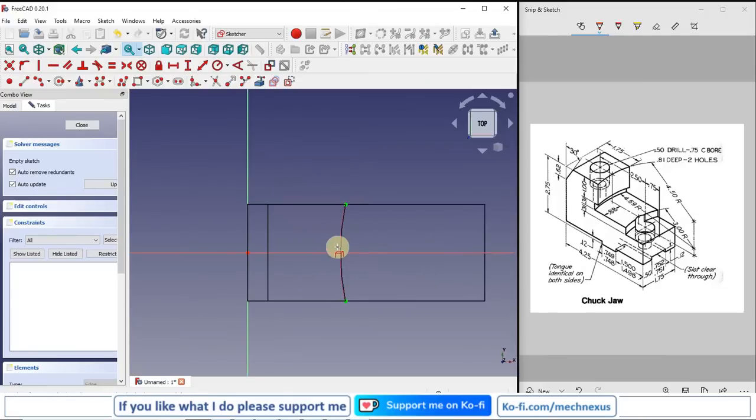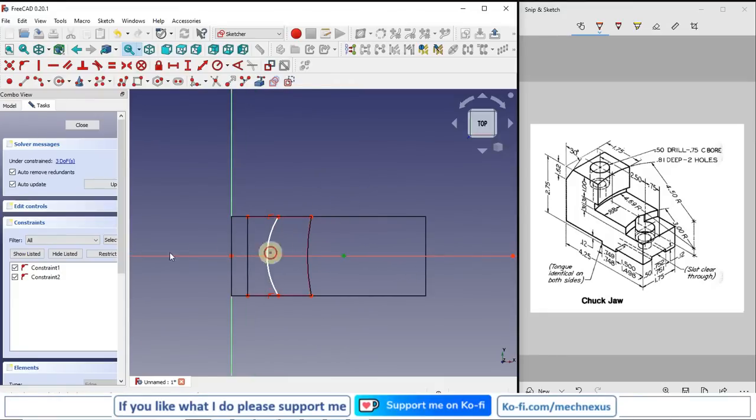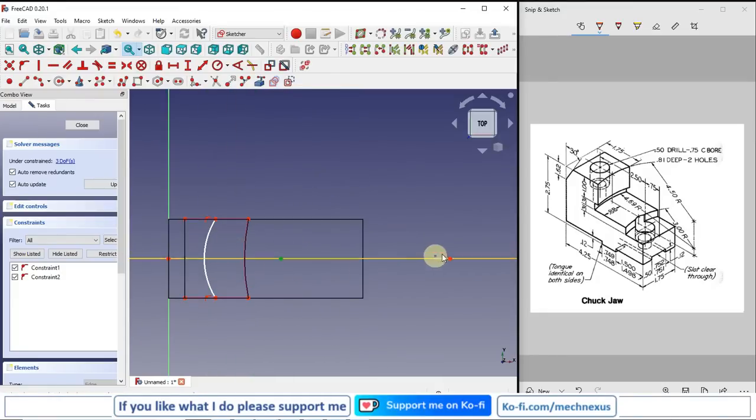So this is our existing arc, so our new arc will be larger than this. So I will project these two corner edges, and I will draw a 3-point arc here. And now these two arcs have the same center, so I will select my existing and my new arc, and I will say merge.